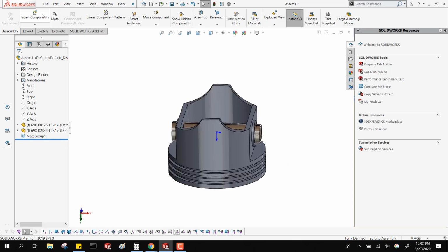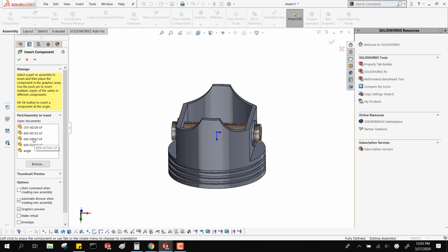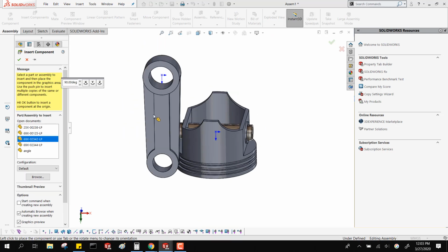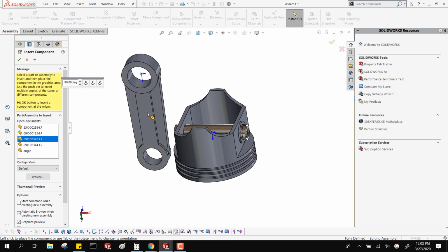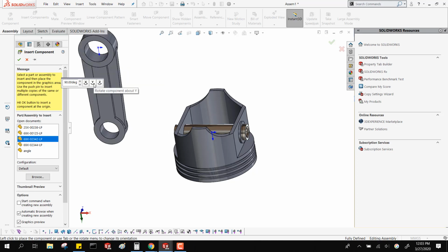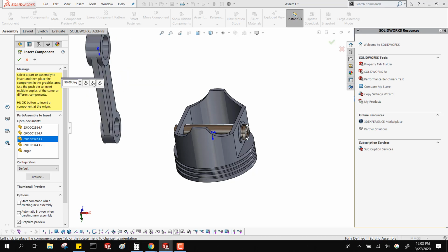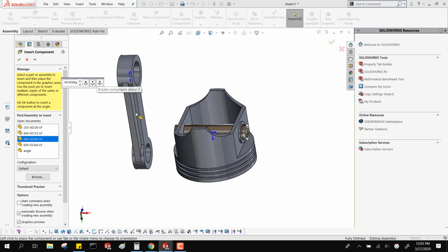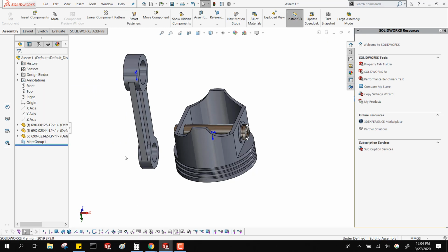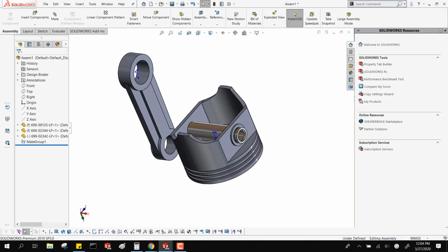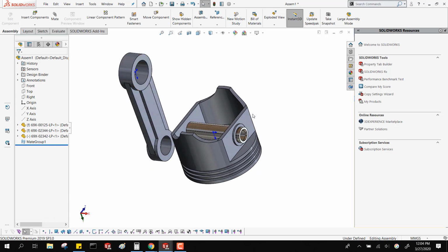I'm going to put in one more component here. One nice thing that they added recently in SolidWorks is this orienter. So when I do move my component onto the screen, if it's not got the right axis, if it's turned a little, I can actually move it in 90-degree increments here using these. It just rotates it about the X, Y, or Z axis, the same axis that you see down here on your triad in the lower left-hand corner.